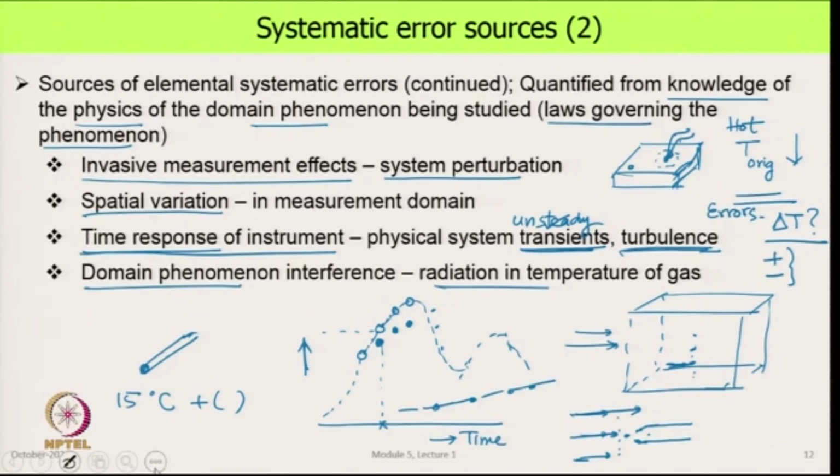So, whose temperature are we reading? Well, it is not the air temperature, but air temperature of the sensor, which is slightly different from the air whose temperature we were trying to measure. The same thing will happen if we take this instrument and say I want to measure the temperature of air, and we go stand outside and there is sunlight coming on it.